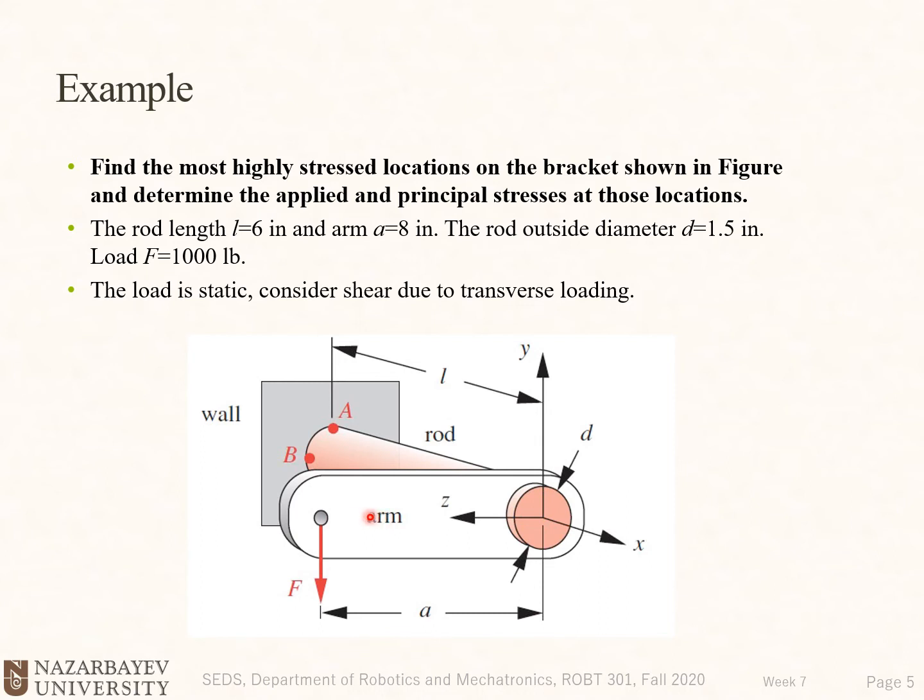Of course, it can be done by FEA analysis and software, but if you want to do it analytically, we don't have to examine all points of the part. We need to find a point with the maximum applied stress, and we know here that the base goes under maximum bending moment.